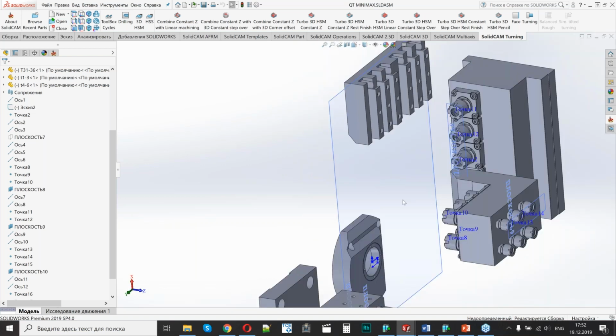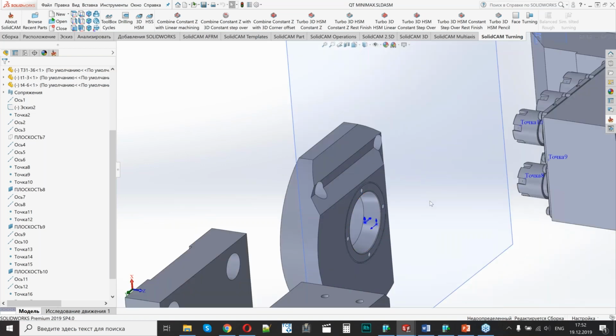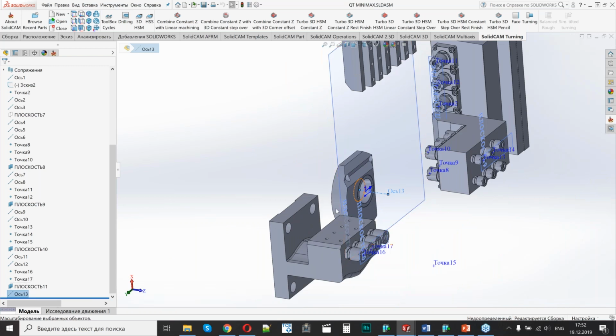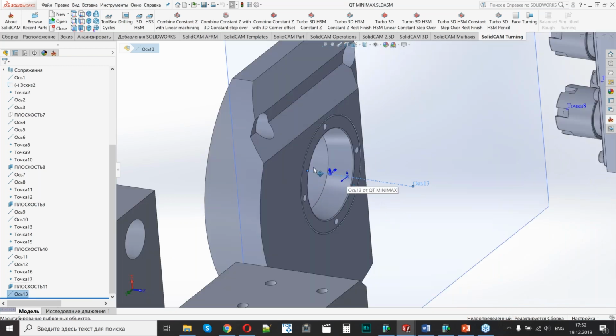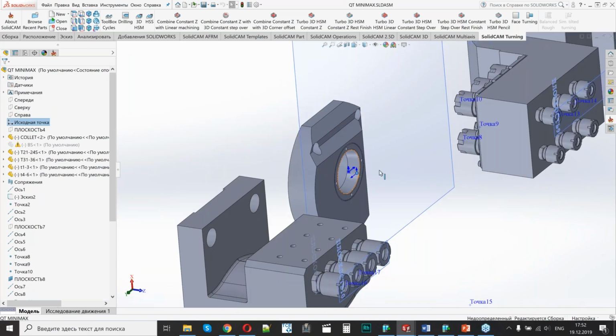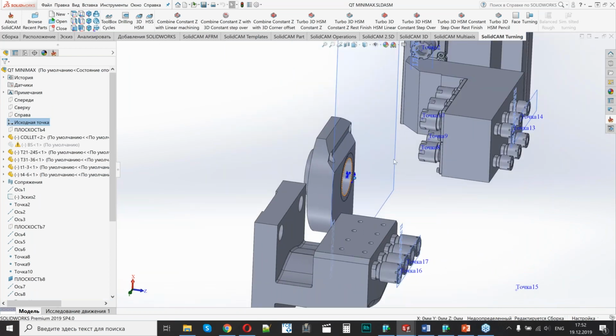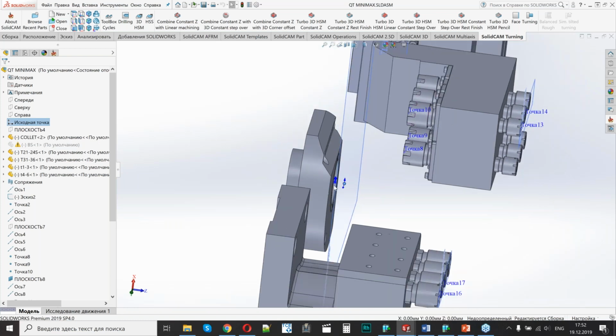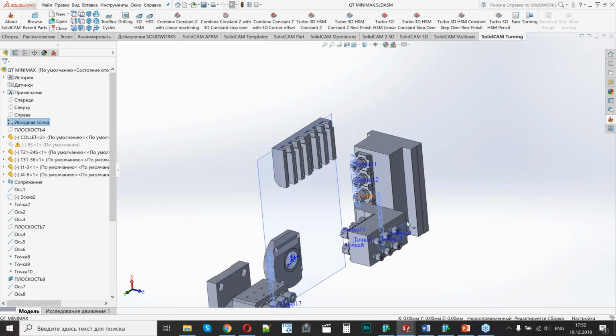The nose of the tool will be exactly on the cross section of this plane and the central line of the machine. And this is what I can have as the 0 point of all assembly. And this will be the 0 point of the machine ID file. It will be here, and this is constant. So this distance is constant. And I will remind you that all these tools can't move by Z. We have our Z1 movement only because of the stock.